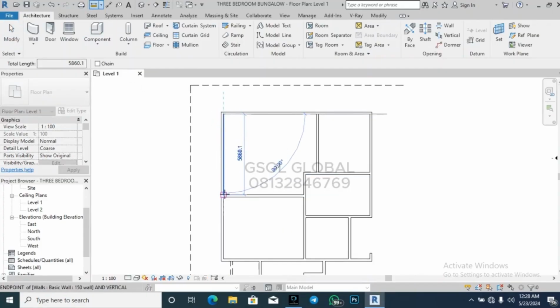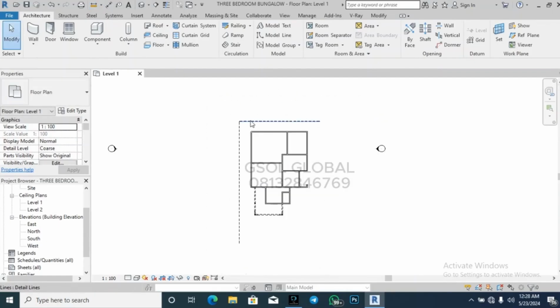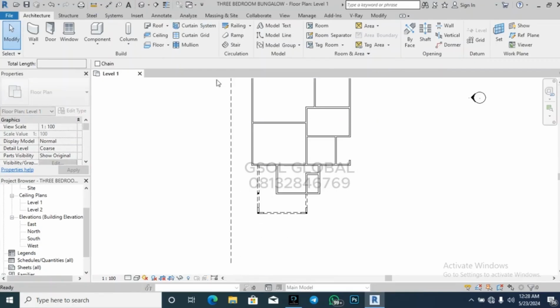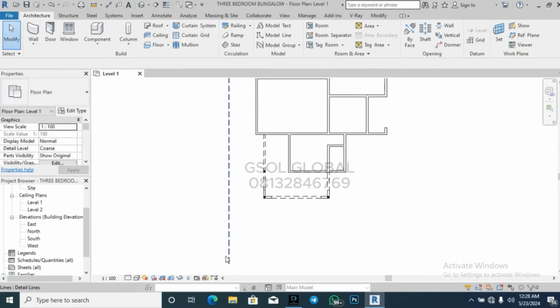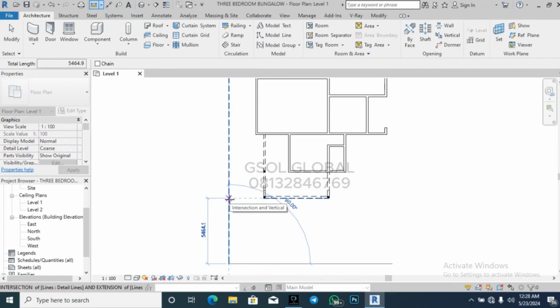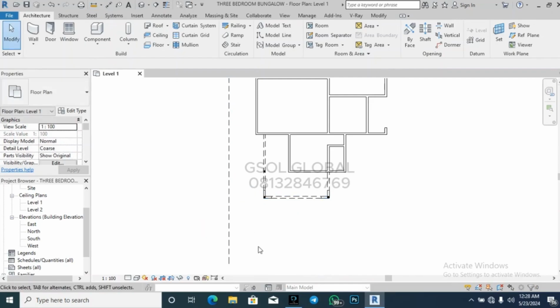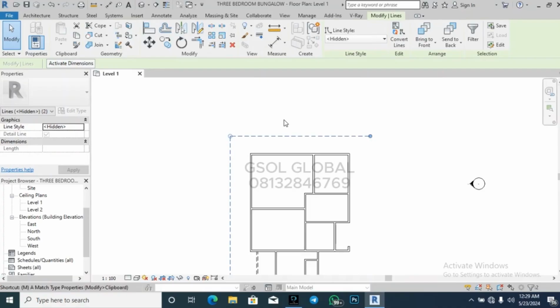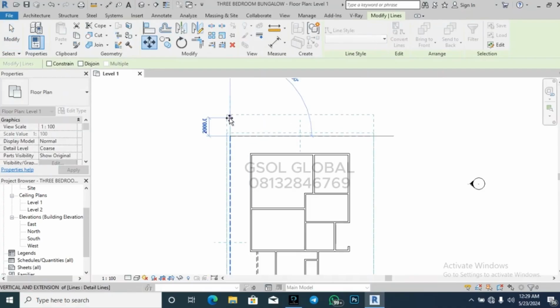We don't have up to 7.2. That's 3.6. Look at this point too. The same thing. So let's see the distance from here to here. A car can park at, okay, we have 5.5 meters, right? A car can also park at 4 meters. So let's see 1.5 from here. So I'm going to shift this upward by 1.5. A car can still park in 3.5 meters, but let's not do too much. 1.5.